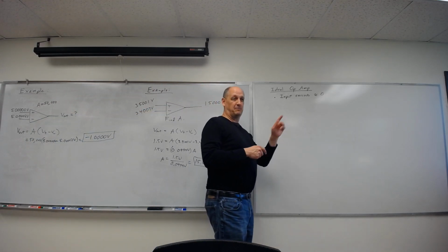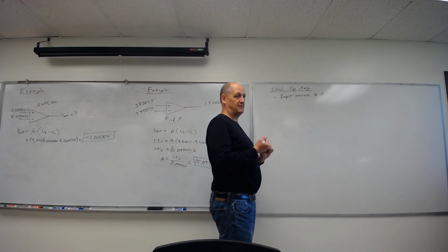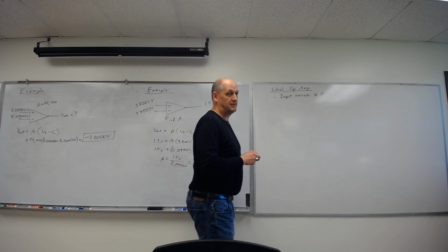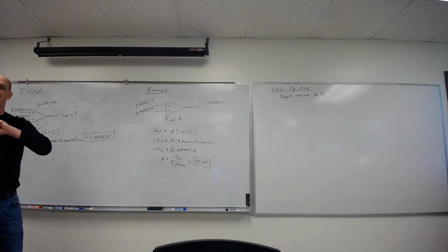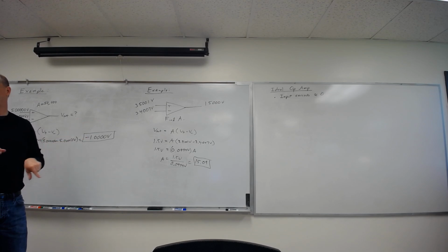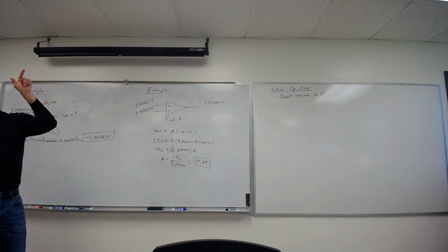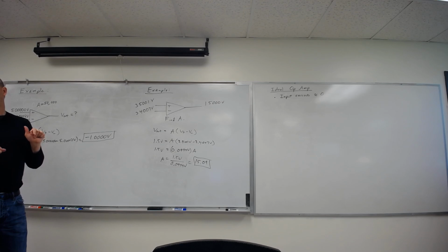That makes solving problems pretty easy. Yeah. So should we expect anything like that to occur in lab? If you have 0 input current, then you won't see an output. If you see an output, that means you have some current. But your current's going to be dinky. If you can measure down into the microamps, okay. But these currents might be down in the nanoamps.